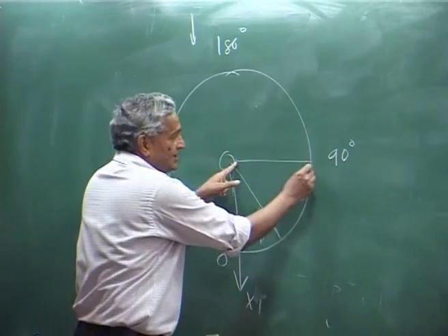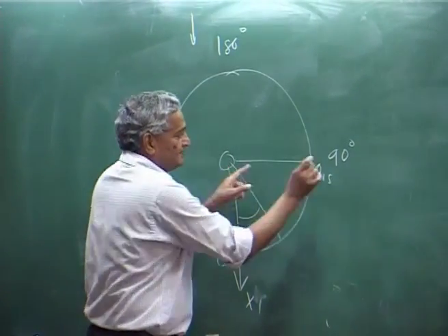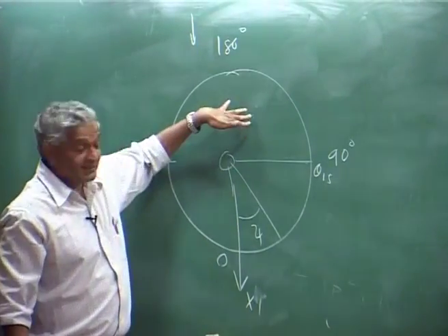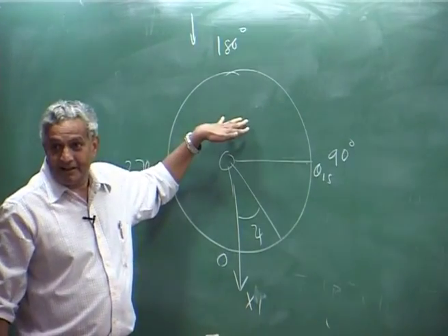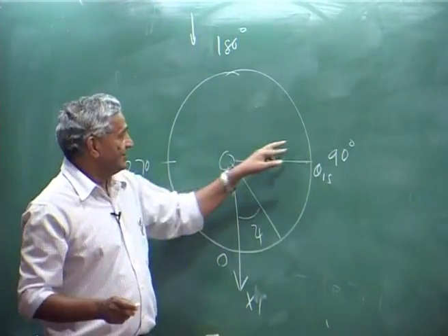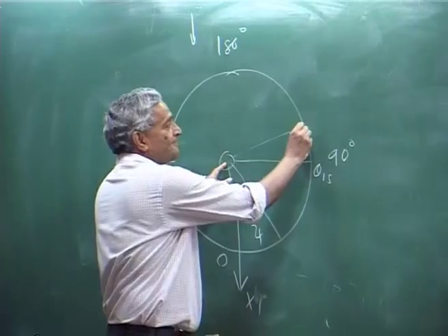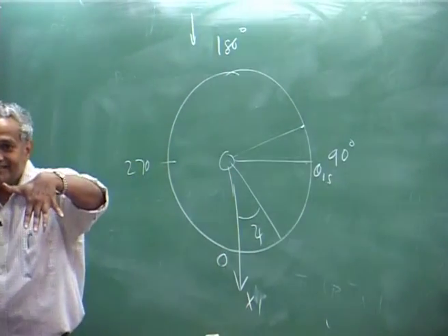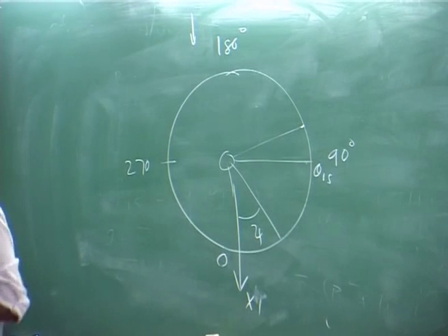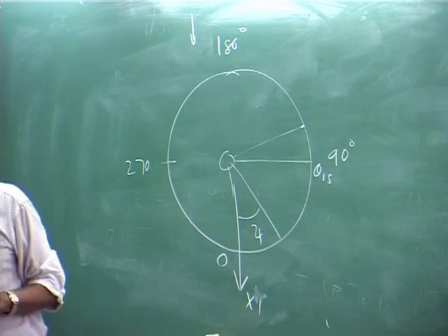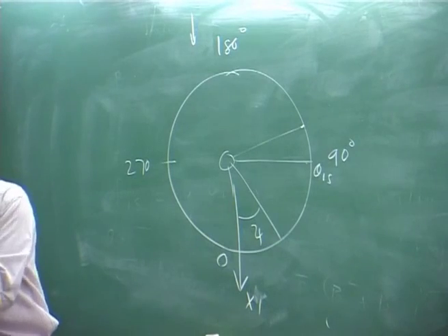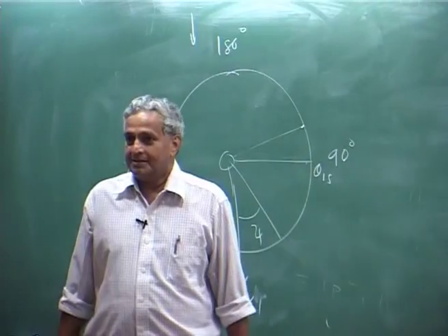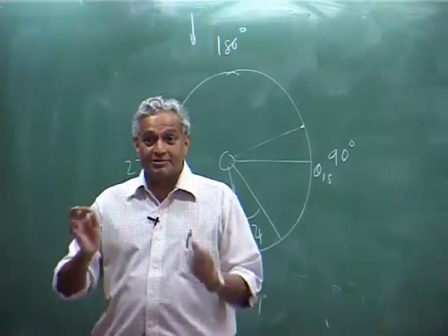If I give theta 1s, what it will do is it will go until here, this will go like this. So, what is normally done is when a pilot gives an input, he will give it somewhere here, so that this rotor disc tilts. So, he will go forward. So, they try to reduce the coupling. That rigging is done in the mechanical arrangement of your control rods.